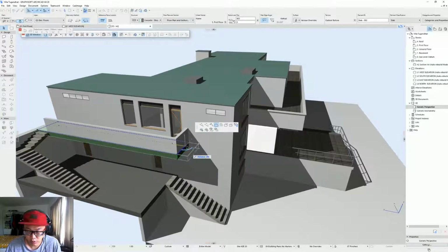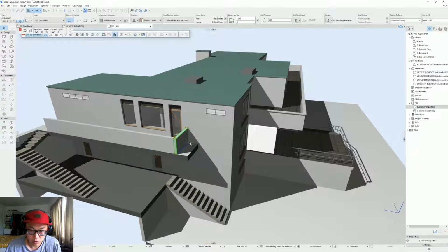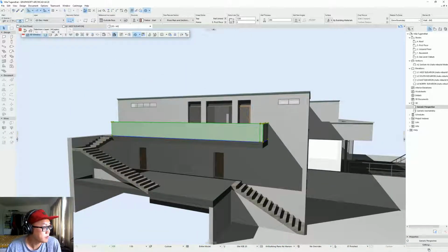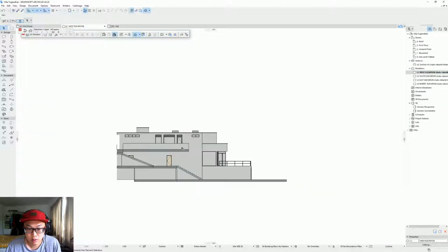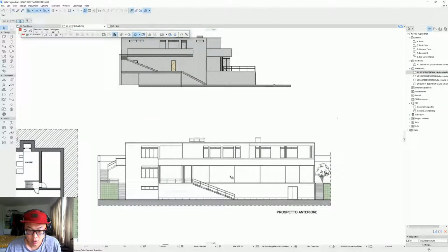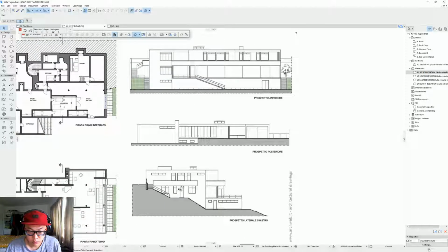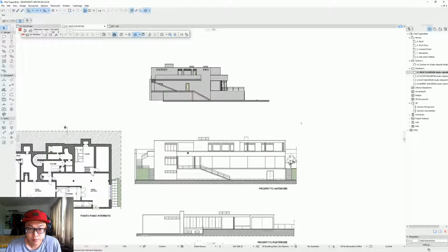maybe increase by 800. Take the wall, Control D, so I can move, and just gonna snap to that point. Select those two, and I'm gonna intersect. And let's go back to the elevation. And now I get 1, 2, and those 3 windows, and there should be a door there. So for those windows, I'm just gonna maybe pick the same one, those ones,